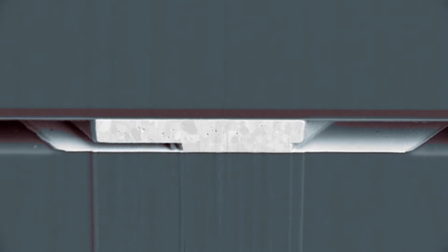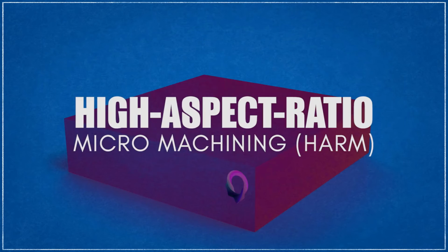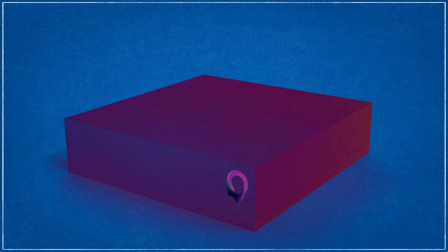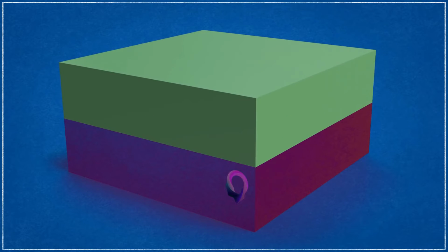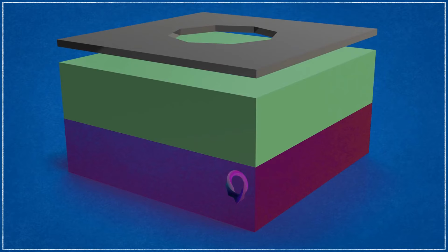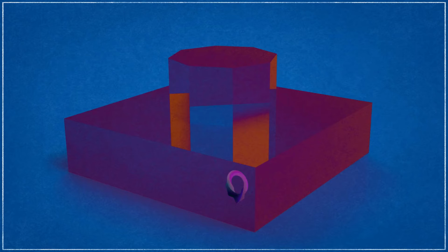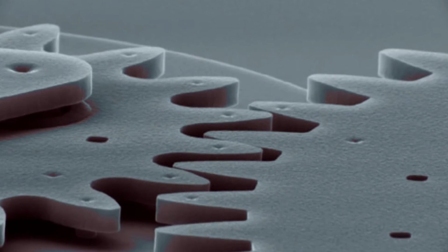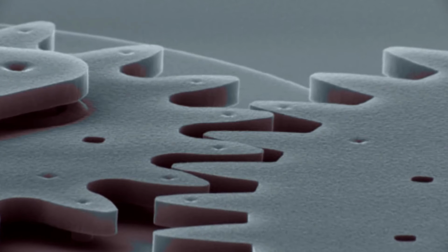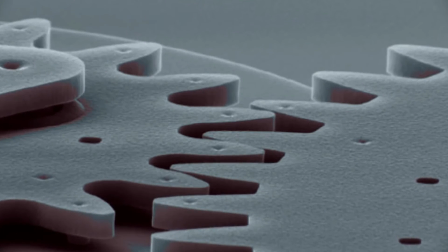Now let's talk about LIGA. LIGA is an important tooling and replication method for high aspect ratio microstructures. The technique employs X-ray radiation to expose thick acrylic resist of PMMA under a lithography mask. The exposed areas are chemically dissolved, and in areas where the material is removed, metal is electroformed, thereby defining the tooling cell for the succeeding molding step.